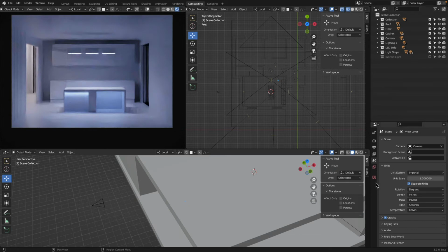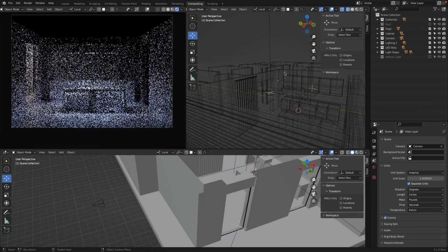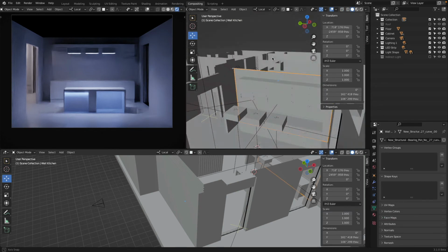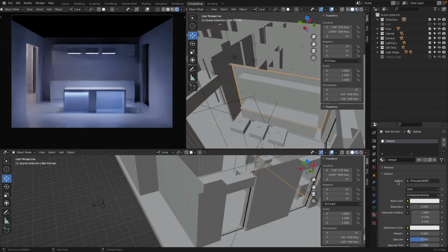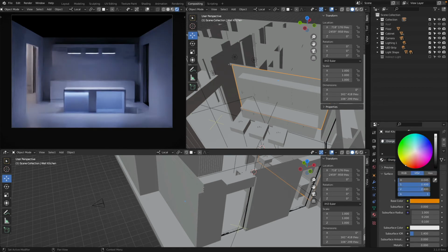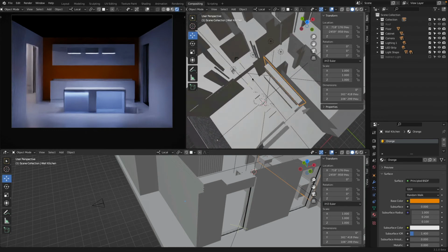So when we explore how light could work, we should actually not ignore materials. So I will, in this view here, I will turn off the roof for the moment. Z and solid, I will select this back wall, go to material, disconnect material because I don't want this to be associated, and new, and call this orange. Base material should be orange. There. Oh, look at that. Looks so much nicer. Well, what about maybe we do something with the hallway?